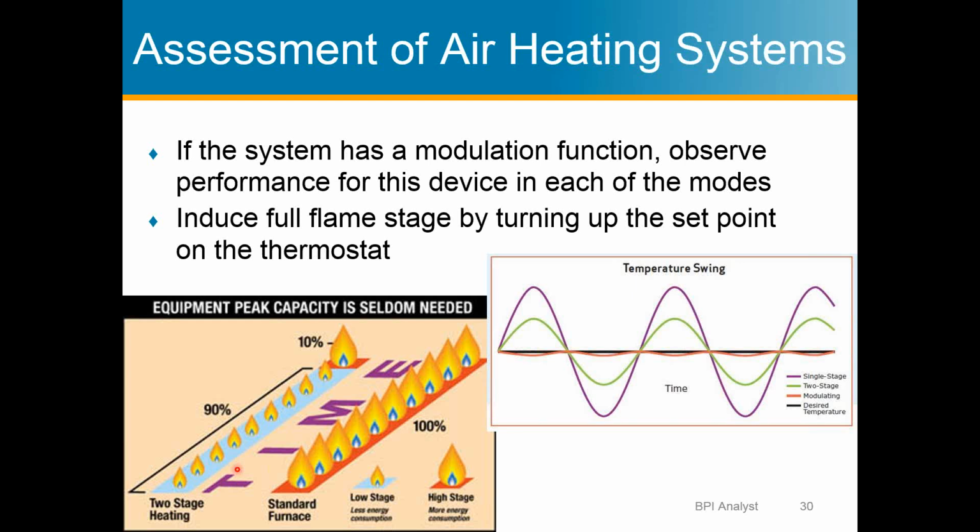On forced air heating systems, the longer they run, typically the better, because the blower is going to distribute air throughout the house better and reduce hot and cold spots. If you have an oversized furnace, it turns on at 100% burn rate, heats up the air and the thermostat really quickly, and shuts off.